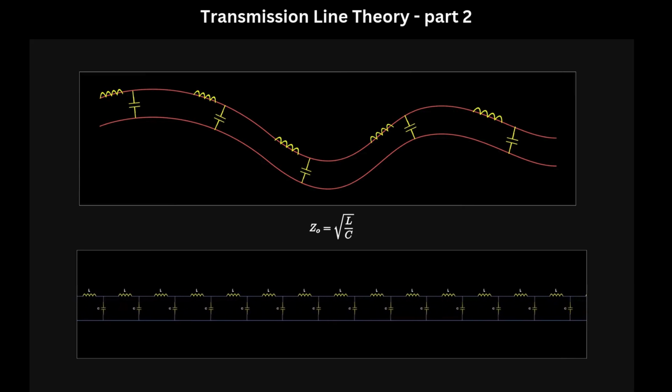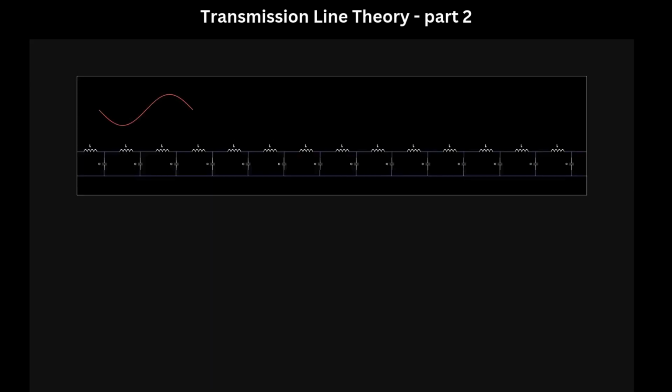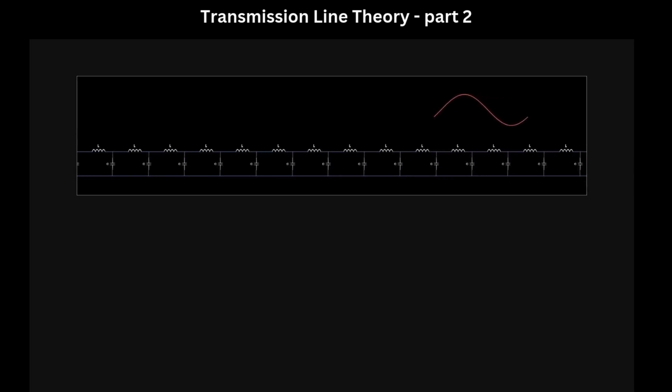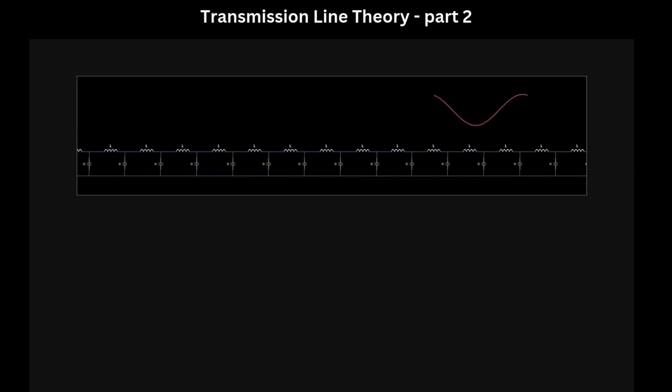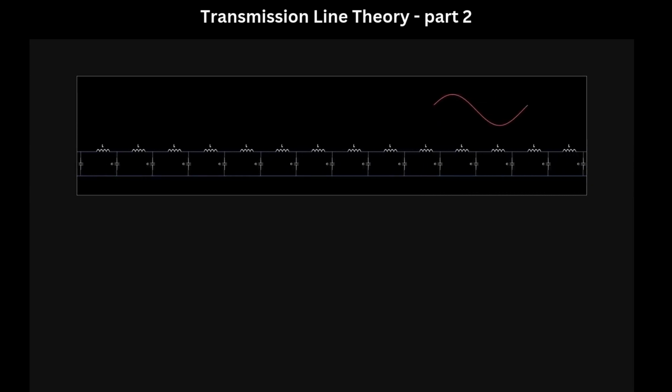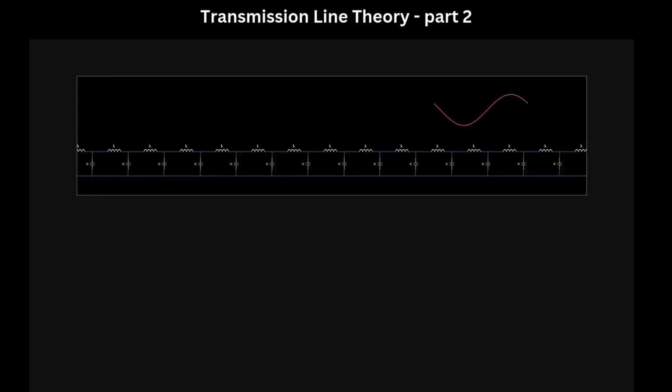This impedance does not absorb power. It only establishes a relationship between the voltage wave and the current flowing in a line. Before reaching the load, while the signal is traveling through the line, it is still blind to any kind of termination on the line. It can only see the characteristic impedance of the line.